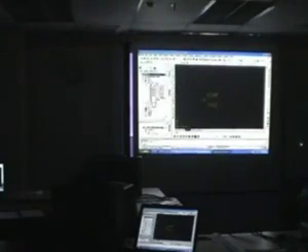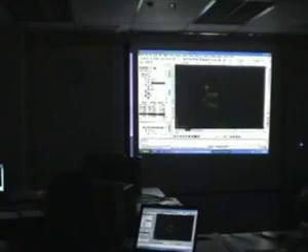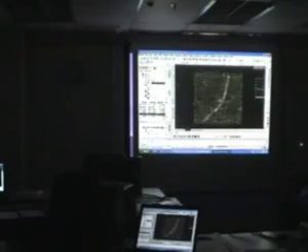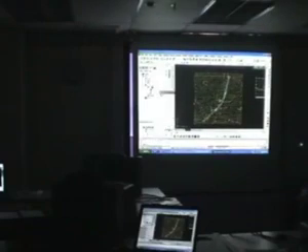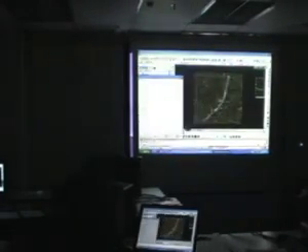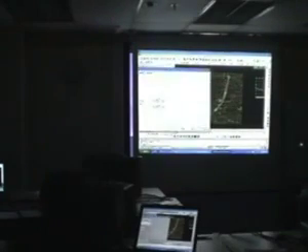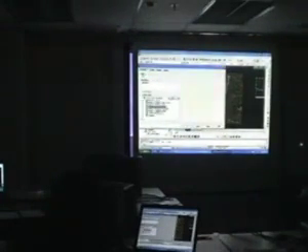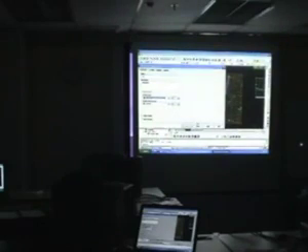Let's say the settings, surface styles. We've got quite a number here actually, borders and contours. Maybe I'll show you the difference between all this. I'm just going to zoom out. I go to the surface, right click, go to properties. This is the surface style, meaning how we're representing the surface at the moment. Right now we're using contours background, so it's barely visible because it's all grey. Let's say I switch. I want to see borders and triangles and directions, and I click apply.